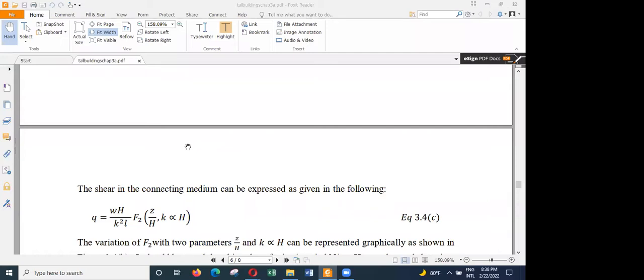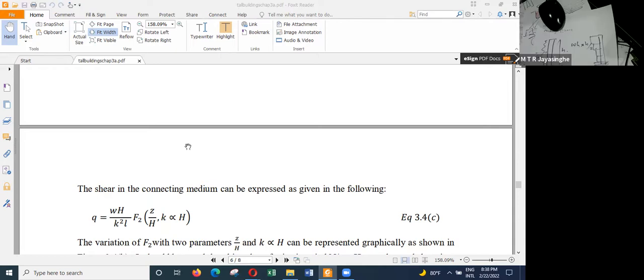There is a question. Many architects now tend to request columns with 200 millimeter width. I have seen during site visits that reinforcing those columns is nearly impossible at joints where all the beams and slabs meet. Can I get your opinion on this matter? Yeah, of course. Tell the architect you can't do it. Don't do things which will make construction of the building impossible, because the architect can draw it, but the structure belongs to the structural engineer. So the structural engineer says, don't do foolish things which will make the construction almost impossible, and the detailing so difficult. You just tell it. That's it.